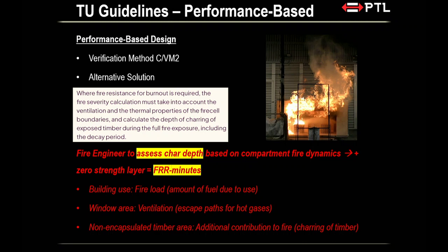Anybody? Any guess? 40 mm, right? 40 mm. If I were to do a calculation based on all these factors, still for a 60-minute fire, I might end up with a char depth of 55. And you as a structural engineer will wonder, what are you doing? Isn't it always 40? Not quite. Not quite when you do a calculation. You read a table, it's 40; you do a calculation, it'll be something else.